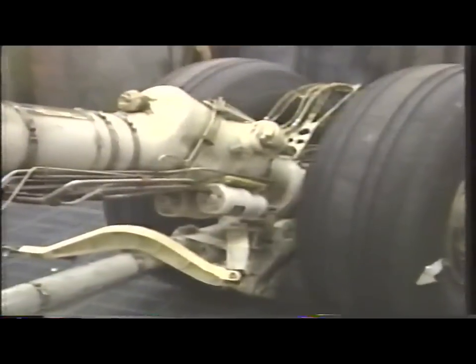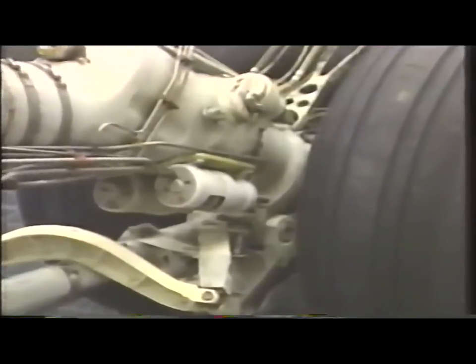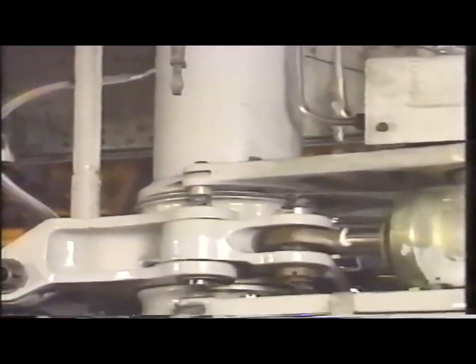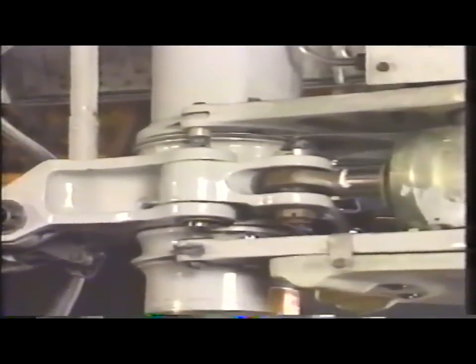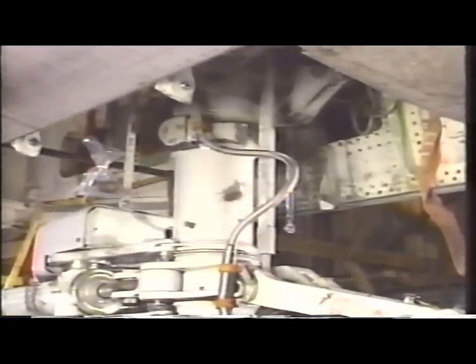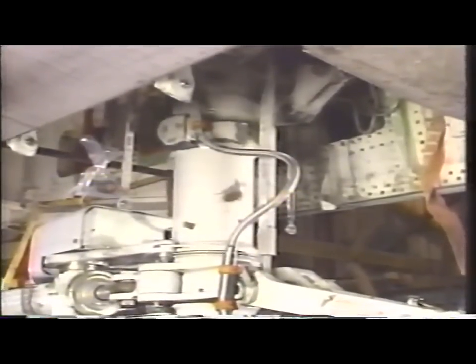There are many trouble spots in the wheel well and landing gear area which should be examined closely during inspections. All high-strength steel surfaces which are subject to corrosion fatigue, all exposed surfaces of struts, oleos, arms, and hardware, much of which is unpainted, exposed electrical equipment, axle interiors, and any crevices between stiffeners, ribs, and lower skin which trap water and other debris, magnesium wheels and bolts, where you may have dissimilar metal contact, and exposed rigid tubing, especially under clamps and identification tape.